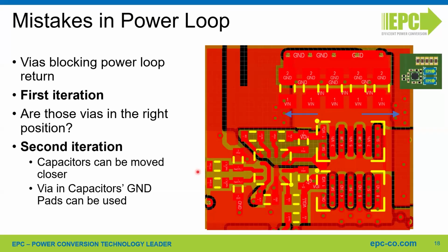For motor drives, we have designs with up to 12 parallel devices, but that is another story. The switching speed in this case is much slower, kept very like 10 times slower than DC-DC, and the layout is less critical, as we were showing in the design example.